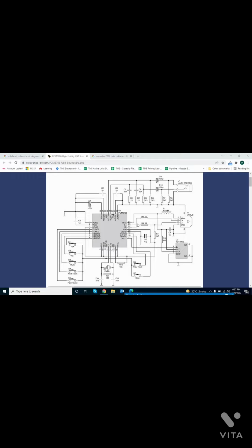Pin number 2 is an internal feedback pin, and pin number 21 is a power pin, 5 volt power, and these are data input pins, and pin 24 is also power input. Pins 29 and 28 are filtered by these capacitors and these microfarad capacitors, and this resistor acts like a load in order to clamp the audio signal going to the main headphone. Now this small little circuit is